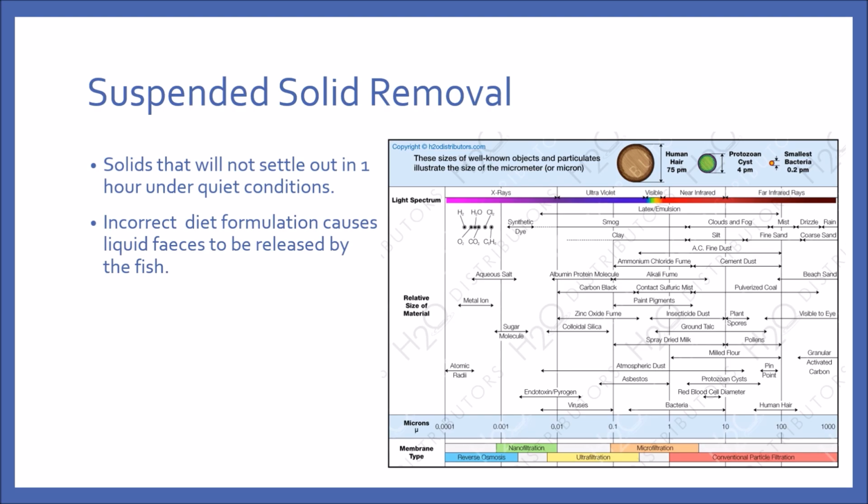The design criteria for any suspended solid remover is to consider the range of the type of solids that you will be accumulating. Sometimes, if you have an incorrect diet formulation, it will cause the liquid feces to remain in the suspended solid form instead of a settleable solid. And you would require a very fine mesh to sieve out all of these liquid feces.